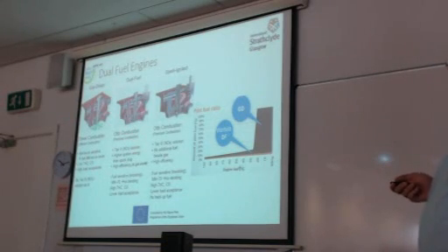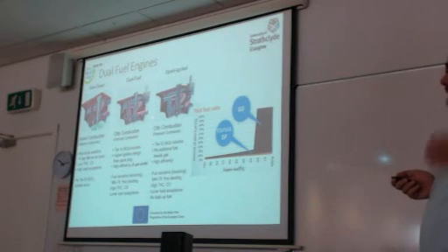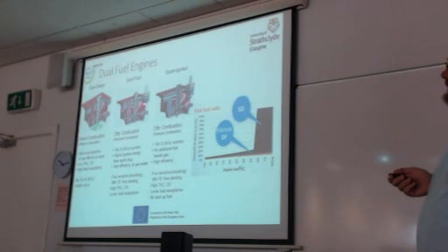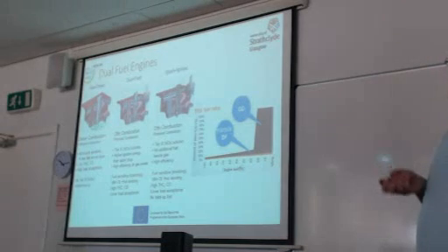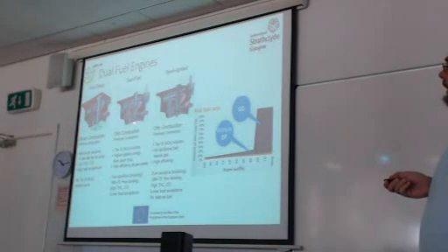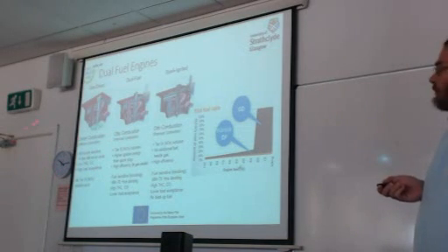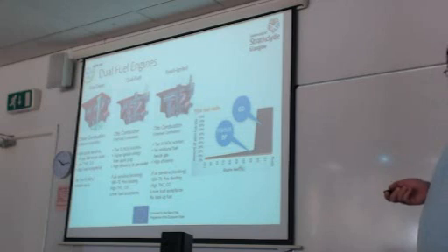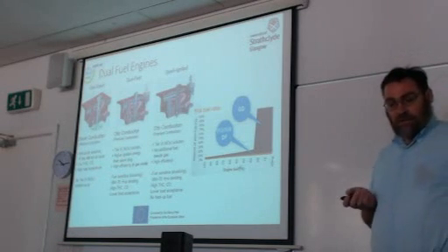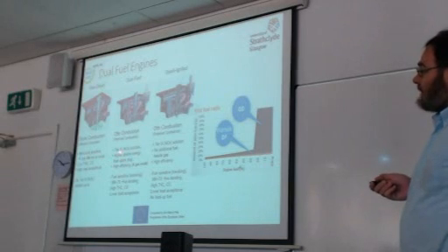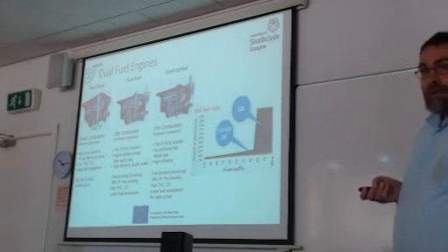So that's the first category. The next category is the dual fuel engine. In this case, as I mentioned, we have premixed combustion. That means that the gaseous fuel will be injected in the port. So we have a natural gas injector in the port, and then at the end of the compression process, we'll have a mixture of natural gas in there. This is the pilot injector. Pilot fuel, liquid fuel, will be injected in the combustion chamber, as explained in the previous slide, and that will initiate combustion.